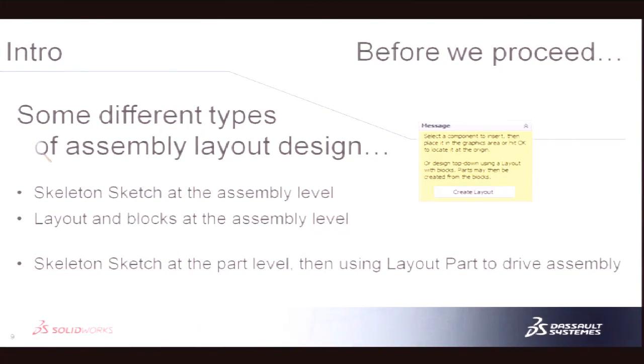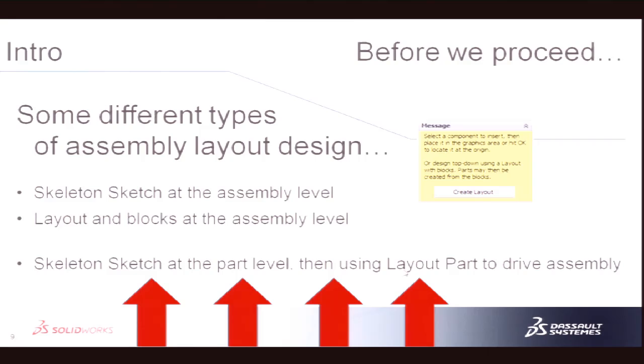Now, there are some other techniques that you can certainly use when you're working with an assembly and doing layout sketches of your assembly. And one of those techniques is to create the skeleton sketch at the assembly level or to create the layout and blocks at the assembly level. And I think that you'll find today that this approach that I'm presenting may be superior, and that is to create the skeleton sketch at the part level and then use that layout part to drive the assembly.